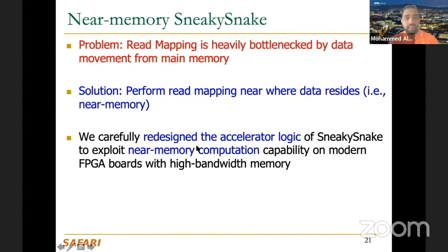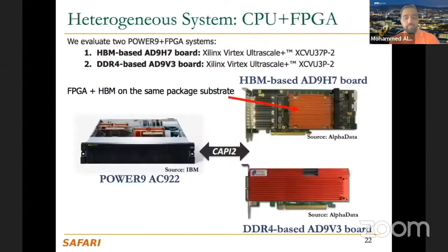That is a capability, a nice feature, provided by Xilinx in their recent boards, and this is the board number. So you can go with UltraScale boards. Most of them have this high bandwidth memory, or HBM, that is located next to the FPGA logic. So you have the memory chip located either in the same package or very next to it.